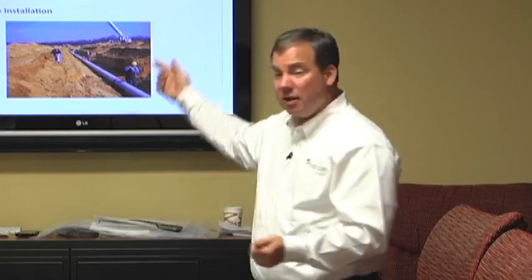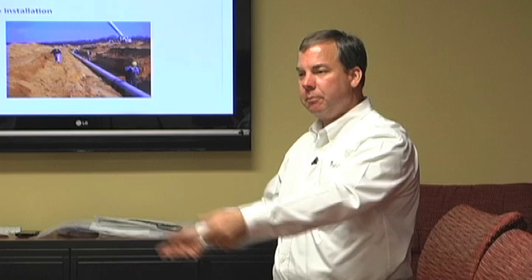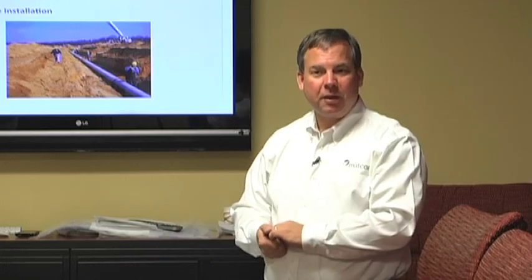We told them, well, we manufacture this linear anode product. I could have that to you in 3 days before you backfill the pipe. If you just lay it parallel to your pipe, you don't have to worry about, am I getting current where I need to go? And it's going to be cheaper. This is a great application for new construction because the cost to install is very minimal. It's just a couple of laborers basically reeling out this anode, putting it parallel to the pipe. And the design certainty is fabulous.